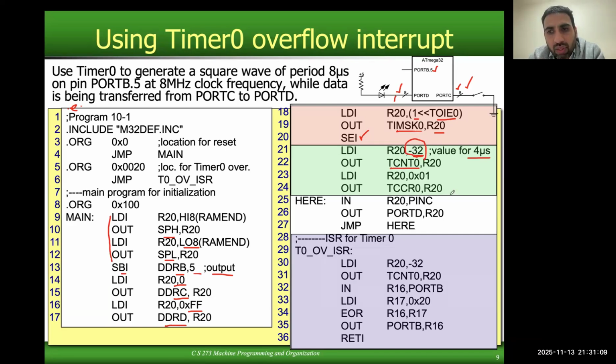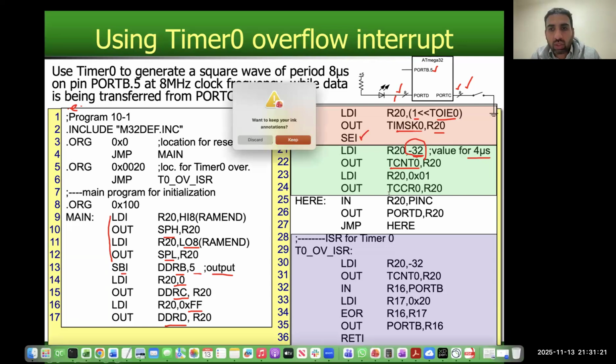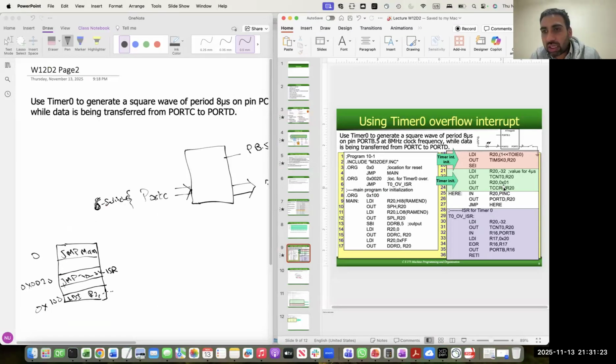And then we need to write the timer control registers A and B. Actually, there is a mistake in this example, in the sense that this example is written for ATmega328, not for 328P.